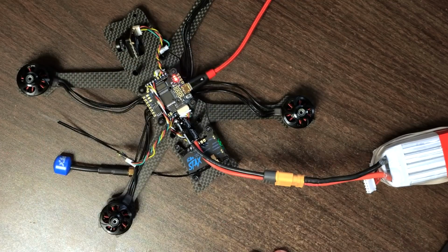And low power disarm until first arm basically says the first time you arm the quad, we go to max power or whatever the power is that you've set it to, and then we stay there until you unplug the battery. But at least with this, if you are plugged in on the bench, you're not overheating the video transmitter.